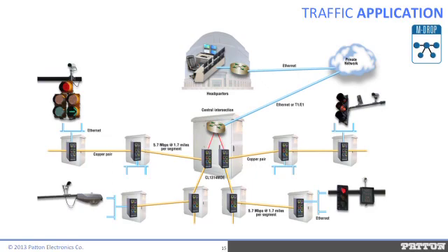The traffic monitoring setup employs two primary sensors. One, video mounted on traffic light structures, and two, sensors installed under the roadway halfway between intersections. The video camera determines if any traffic is waiting at an intersection. The sensor senses the traffic rate of flow. The sensors transmit their information to a control box located at the intersection, which then adjusts the traffic signal timing according to live conditions.